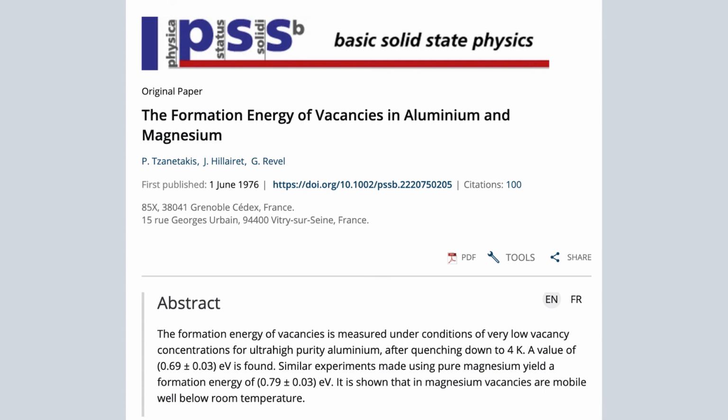Okay, to wrap this up, we spent a few minutes developing a flowchart which we ran. Calculated the vacancy formation energy and got about 0.85 eV for aluminum. And as you can see from this paper, the experimental value is just under 0.7. So we have a reasonable result.